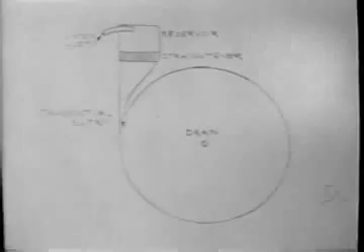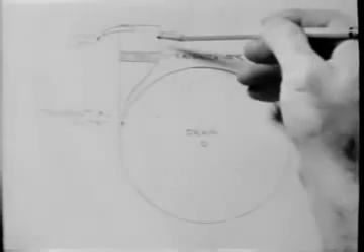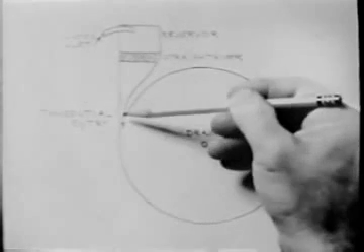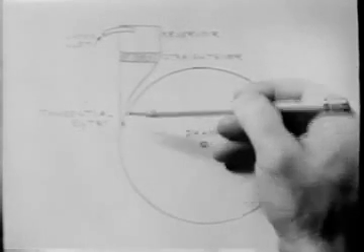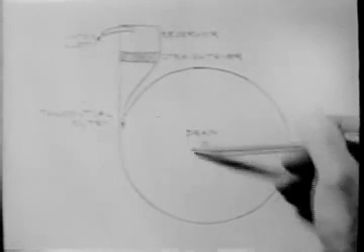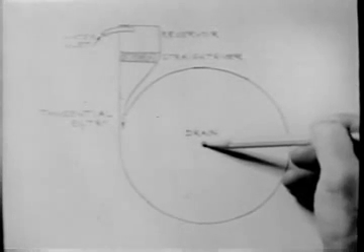On the other hand, the flow may be without rotation, even though it is curved. This is the plan view of a spiral vortex tank. Water passes from the reservoir through a flow straightener and into the tank through a tangential entry. It spirals round and round in a very tight vortex and finally leaves vertically through a drain in the center.